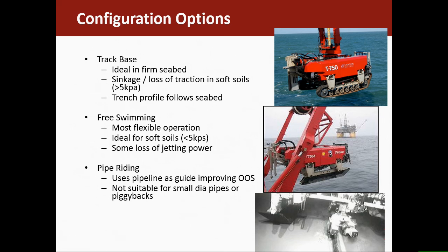And there are some configuration methods that you can choose. You can have it on a track base, drive along the pipeline, and I would argue that's usually the best one, because you've got good control of your speed and currents aren't trying to push you off sideways. So most of the operators I know prefer to work on track bases.